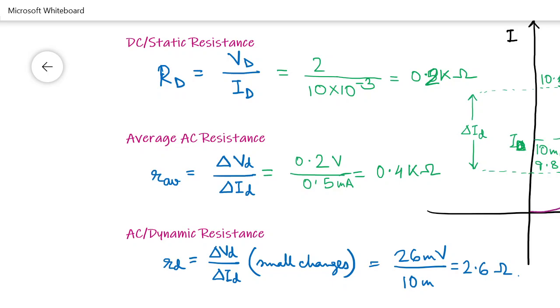When you apply a reverse bias, there are only minority carriers contributing to the current. This minority carrier current is called the reverse saturation current. In the forward bias region the minority carriers are also there, but you are not able to visualize their contribution separately. When you make it reverse bias, only the reverse saturation current is present.